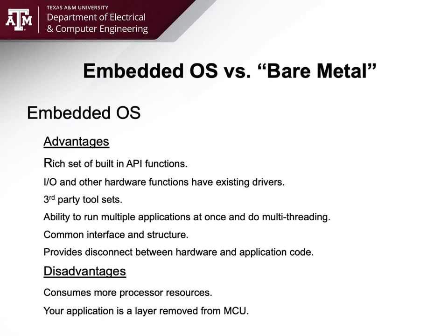You still have to write code to support what they call the API, the application programming interface, which may or may not save you a little bit of work. Some of these peripherals are so easy to use that the API function is really just an extra step you go through. But if you're doing TCP/IP functions, unless you have a library for it, you have to write that code. So it's kind of nice to get it already existing.